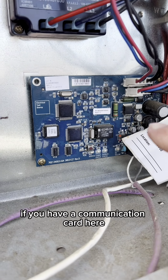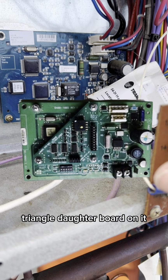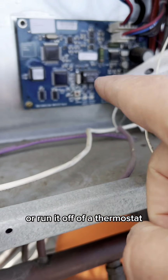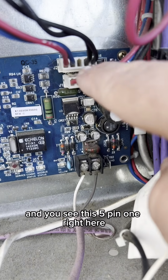If you have a communication card here, like this LCI, or a BCI for BACnet that's red, or a TCI, which has the little triangle daughter board on it, and you need to run this unit in standalone or run it off of a thermostat, what you can do is simply turn the power off to the unit, come to this unit here, and you see this 5-pin one right here.